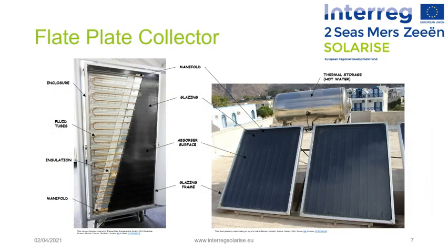A typical flat plate solar collector is composed of a black absorber surface of high absorptivity, where a large portion of solar radiation will be absorbed by the plate and transferred to the transport medium in the fluid tubes to be carried away for storage or use. The liquid tubes can be welded on the absorbing plate, or they can be an integral part of the plate. The liquid tubes are connected at both ends by large diameter header tubes, so-called manifolds.